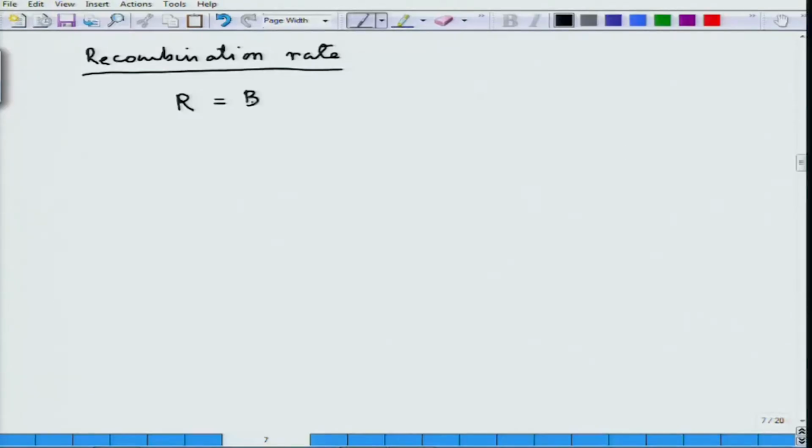So, my recombination rate from the last lecture is some constant because of the first mechanism, let us say band to band transition, multiplied by the carrier concentration in the conduction and valence band, plus the rate due to the second process through the RG center, for example, again NP, plus the third process maybe due to excitons, and so on. I can add all the recombination generation processes that I have talked about, or maybe there are more, and I will get the total recombination rate.